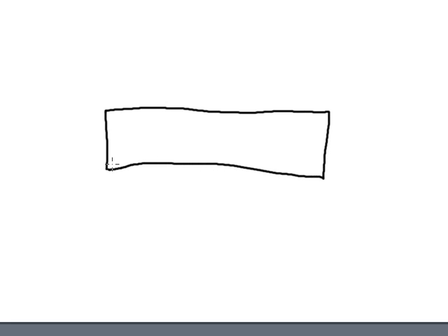Well, let's say we've got a 4-bit adder here. Inside this 4-bit adder are just four single-bit full adders, where the carry out of the least significant bit goes into the carry in of the next bit. But just to save some writing, I'm not going to write them all. We're going to have A3 and B3: A3 goes straight in, but B3 gets inverted.